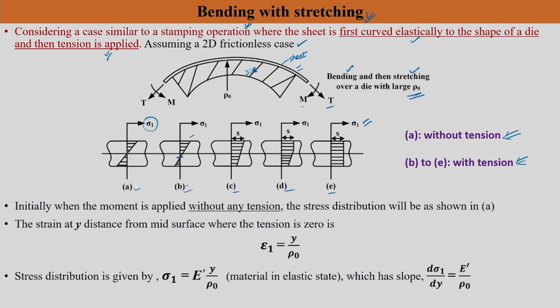Right. So, now C, D, E are further stages of providing tension. Okay. C is little specific. Why? Because you are providing tension such that your plane strain yield stress is reached at the upper surface, okay, at the upper surface, and if you further progress it, the plastic deformation region will propagate throughout the section. So, you see that S is here, now S is up to this particular thickness. Now, in the last case you will see the section is fully plastic, so that your S flow stress is reached fully throughout the section. This is T, this is your sheet thickness.